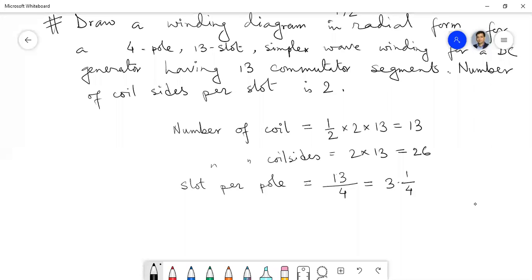Now, next thing which we have to determine related to armature winding is the back pitch. Back pitch, you know the same formula, twice C by P, for progressive we should take. Anyway, plus K you just take, minus also we can take.